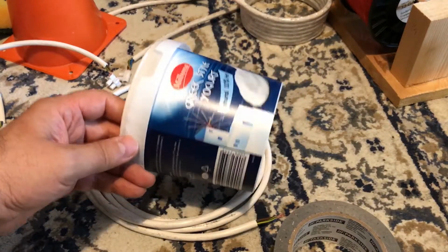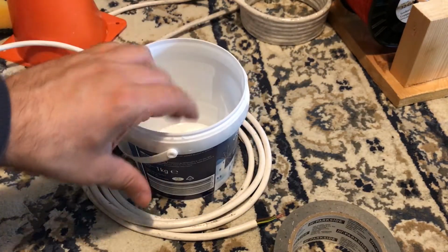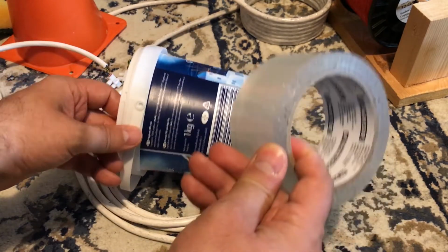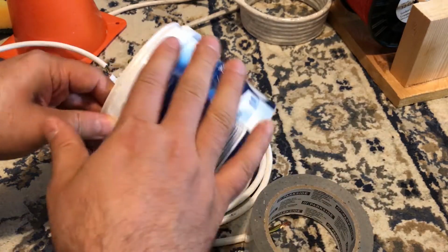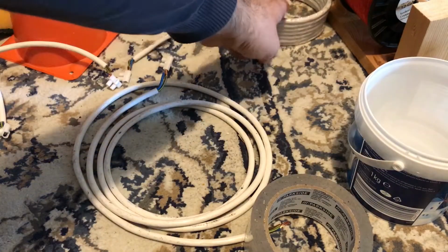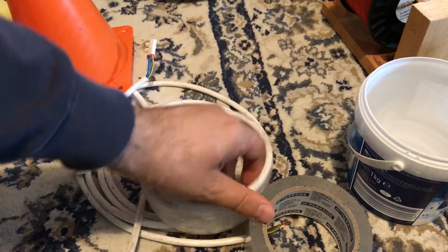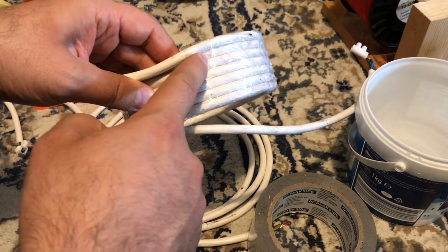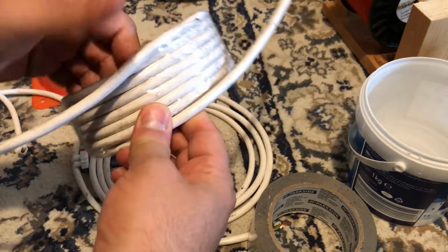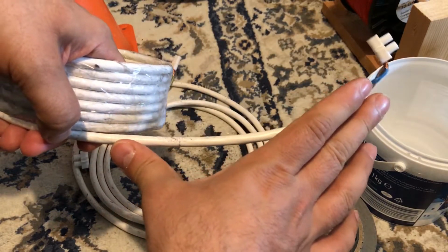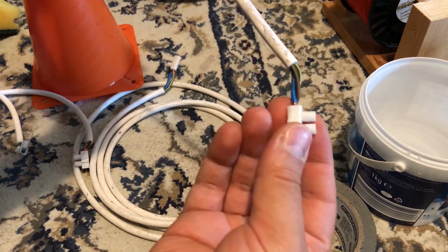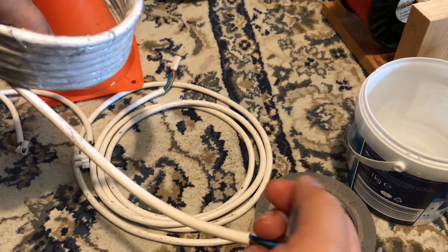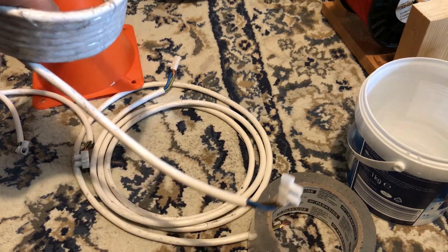So then I use a yogurt container and I wrap the wire around this, and at the end put some packaging tape on it, and then when it's a bit solid you can remove it. This is the outcome. So this is the primary winding that I made. It has in total 7 turns, and approximately 20 centimeters from each terminal. So all of the wires are connected together. And then this one will connect to the rest of the circuit.